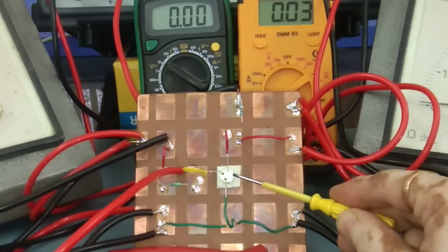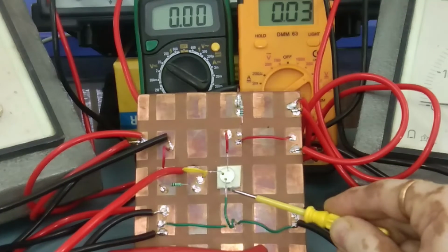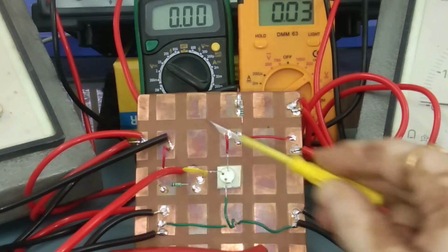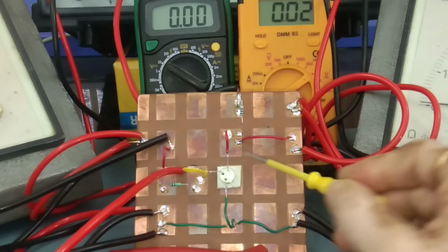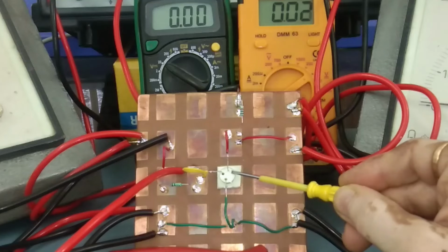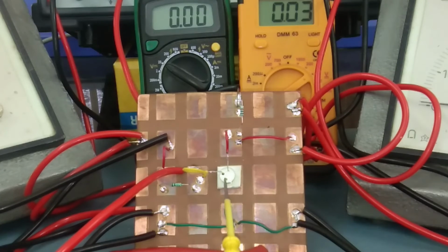This is the transistor, and here you can see the notch. The nearest terminal to the notch is the emitter. After that there is the base terminal, and then there is the collector terminal. You can find very easily that the collector terminal is connected to the body of the transistor. On this side of the transistor we have the collector circuit, and on this side we have the emitter circuit.